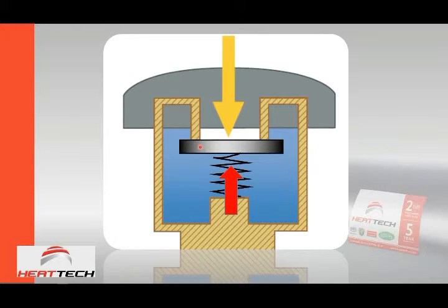It is like an orifice plate, a seal that is kept in place by means of a spring. So under normal conditions, this is what a vacuum breaker looks like. It's got the seal kept in place with a spring, and the more water pressure you have, the tighter it pushes against the sealing surface.